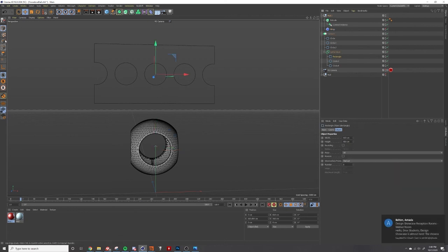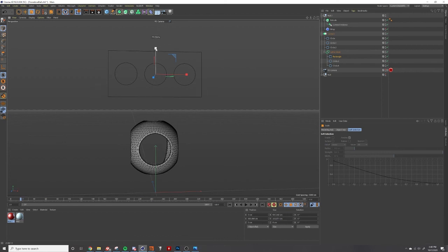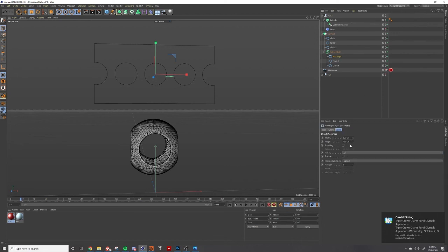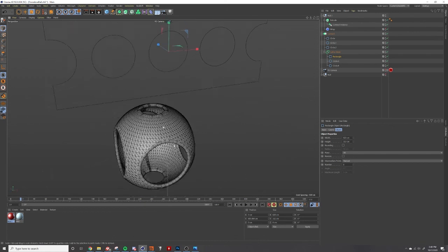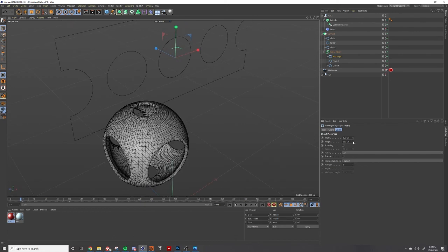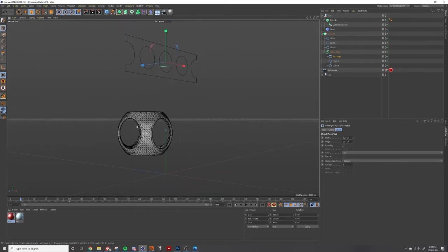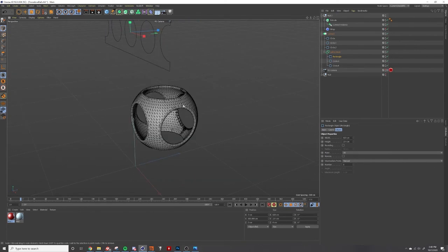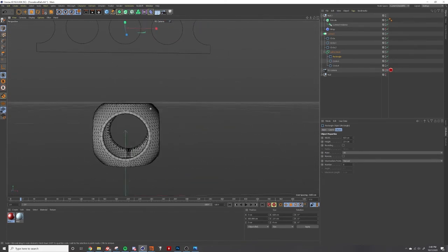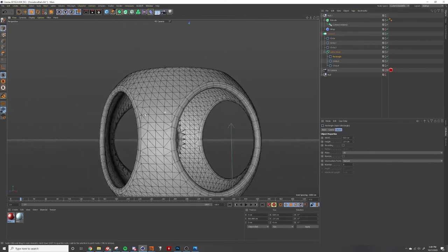So let's take our rectangle and our scale, and let's just scale it down vertically. Oh, hold on. Let's go into our numbers and we can just change the height. So let's bring the height down, and you can see as I do that, it'll automatically calculate this hole for me. And when I think it's about right, compared to the other circles, I can stop, and there you go. There's that wonderful shape that's near impossible to make otherwise, that is ready for texturing and good to go.